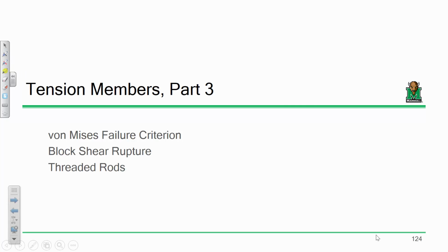It's probably more just because of stuff building up and just the joint not performing the way that it should. Expansion joints are always maintenance problems, so they really are. I joke in concrete design that there's only two types of concrete in this world, and that's wet and cracked, but that really isn't a joke when you talk about maintenance, because yeah, it's challenging.